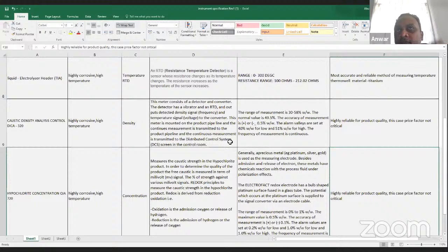So you will have moisture and also chlorine gas. In this case, you have a two-phase. But what you are going to measure is the moisture content in the gas. So you will select a moisture meter. So this is one example: what you actually want to measure will determine what instrument you choose.